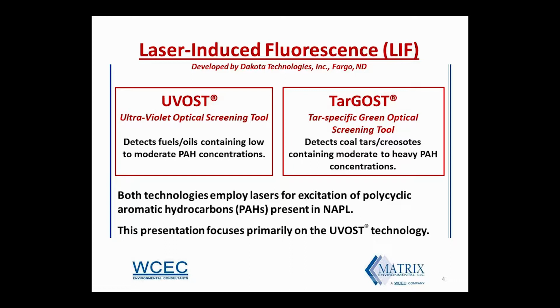The ultraviolet optical screening tool, or the UVOST, was the first LIF tool developed by Dakota. It was initially used at a wide variety of petroleum-impacted sites, but they pretty quickly realized that the UVOST was just not performing reliably for NAPLs containing moderate to high PAH concentrations, so they developed the TARGOST technology. The TARGOST is used to detect coal tars, creosote, and other heavy petroleum products with relatively high PAH concentrations. And the UVOST is now primarily used for sites impacted with lighter-end petroleum products containing low to moderate PAH concentrations.